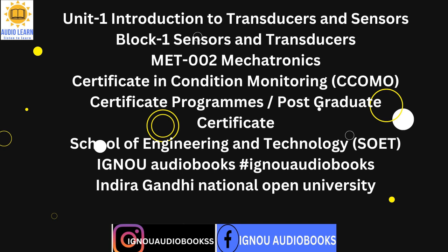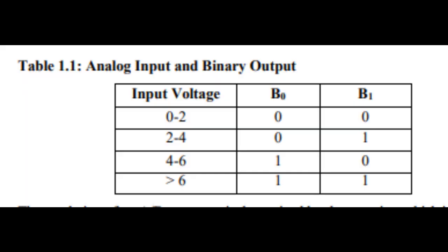An AD converter has 2^n discrete quantizing levels, where n is the number of bits in the register of the AD converter. Figure 1.5 illustrates a 2-bit AD converter with a full range voltage of 6.0 volts, i.e. it is designed to be used over the range 0 to 6.0 volts. The mapping of voltage into a binary count is shown in Table 1.1. An AD converter maps a voltage range to a binary count.